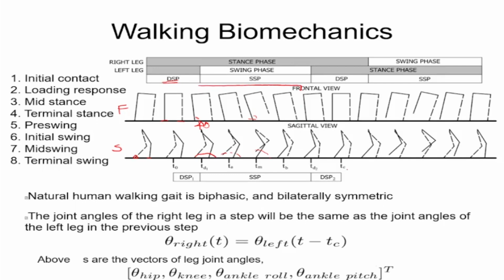again. Now in double support phase, again the robot bends on the other side. So in the next DSP, what will happen? It will bend on that side. In this case, it was bending on this side. So DSP, SSP, DSP, SSP, and it is going to bend alternately from one side to another side, and the rear leg is moving forward.